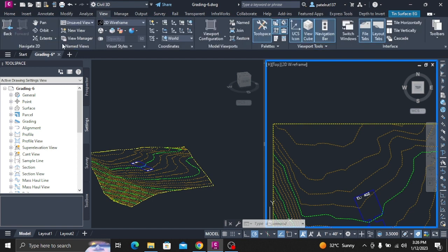To adjust the arc tessellation, a surface must be created from the grading group. This surface is temporary. You will delete it after you have adjusted the arc tessellation. In the Grading Group Properties dialog box, on the Information tab, change the tessellation spacing setting to 1.000 foot. Click Apply. Clear the Automatic Surface Creation checkbox. When asked if you want to delete the slope projection grading surface, click Yes.